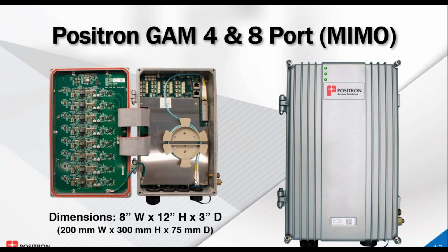And then, this opening here is for fiber. On the left is the opening for copper. And then you have punch-down blocks, so you can assign 1 or 2 pairs for each of the ports. And the main circuitry of the GAM is on the right inside this device, and in the cover we have the reverse power feed circuitry. So you patch the pairs here. They have G.hn and power. We extract the power and bring it here.